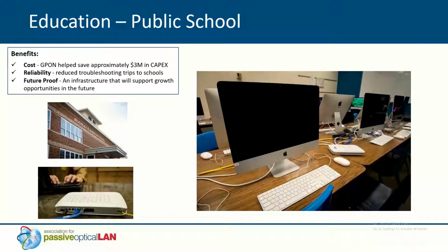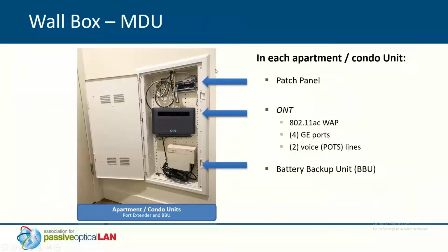And what that means is, let's say you've got 4 walls in a room, a classroom, for instance, and all of those wall jacks go to the same splitter. That allows a teacher to, let's say, move his or her desk from one side of the room to another, unplug that ONT from the wall jack, move it to another. The ONT will come back up, and because it's on the same splitter, the same config will come up. And just another option, and a way to look outside the box in cases where it makes sense.